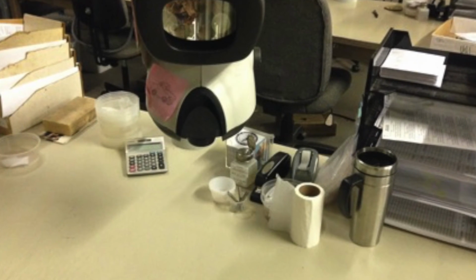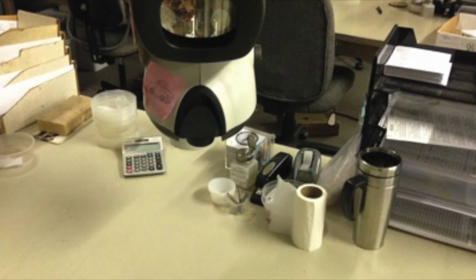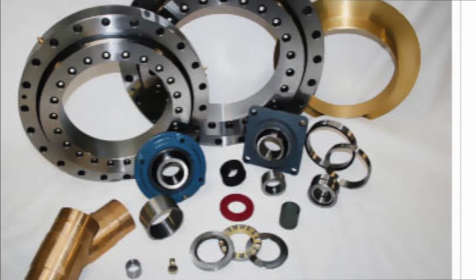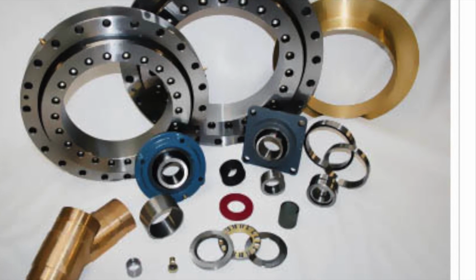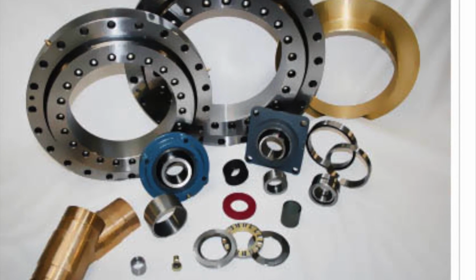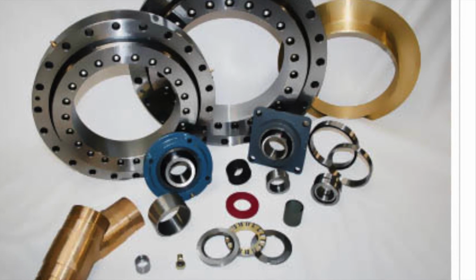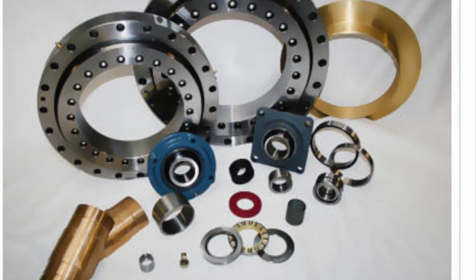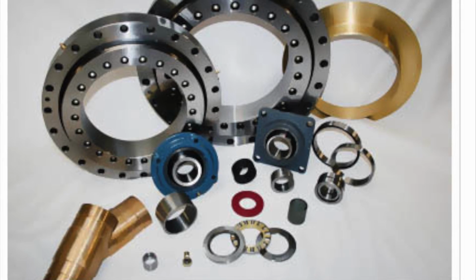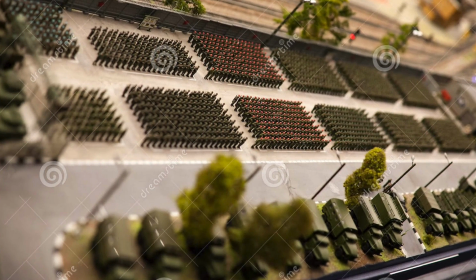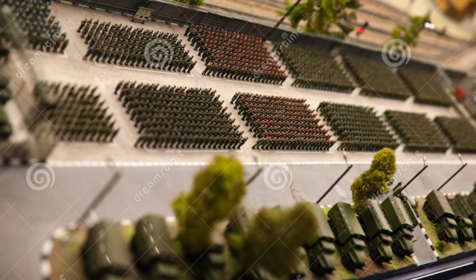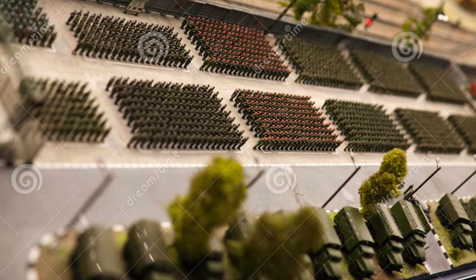All of the parts are in the box. And then the quality standard comes into place, the actual physical appearance of the work. In addition to just cutting the leads to a certain length, are the cuts straight? Are they the same length? Does it look right? If you line them all up, do they look like 100 little soldiers that are nearly all identical when you pile them out there, things like that?